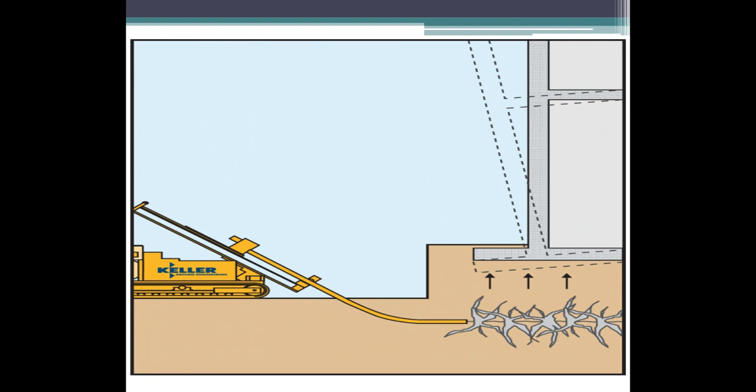Okay. So by using this type of grouting technique injected at high pressure, there is a formation of lens-like structures which heaves the ground and makes the foundation straight.